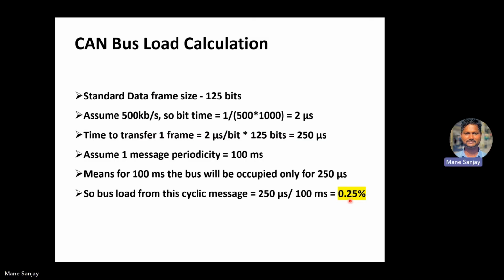So this is everything I have covered for the CAN protocol, starting from the CAN structure and different terminologies like CAN controller, CAN bus, CAN transceiver, main microcontroller, that is a CAN node. Then termination resistance: why we need 120 ohm termination resistance. What is a CAN frame, the acknowledgement field, data field, CRC calculation, delimiter, end of frame, DLC, everything we have covered. We also touched on different questions, as well as the use of bus load and how we can calculate it. So this is how CAN is covered.